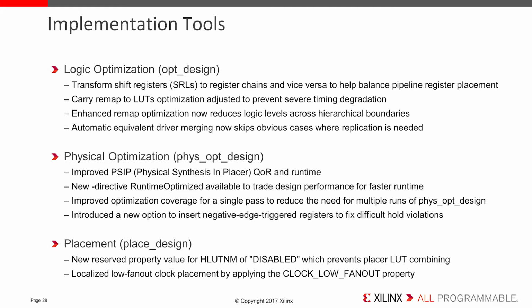And the equivalent driver merging optimization avoids merging obvious cases where replication is needed, such as equivalent drivers in different P blocks. For physical optimization, a subset of Vivado phys_opt_design was included in the placer and became known as PSIP in 2017.1, short for Physical Synthesis in Placer. This gives better performance in 2017.3 as many outliers were analyzed and fixed.